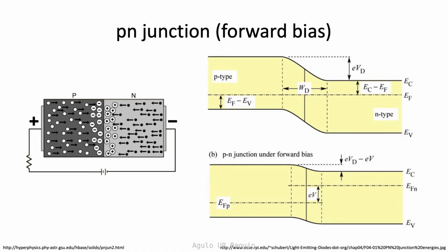And the energy barrier needed for the electrons and holes to move to the p-type from the n-type, respectively, becomes smaller. At some applied potential, the conduction and valence bands of both regions align and charges freely flow from one region to the other. Thus, at some given potential, current increases significantly.